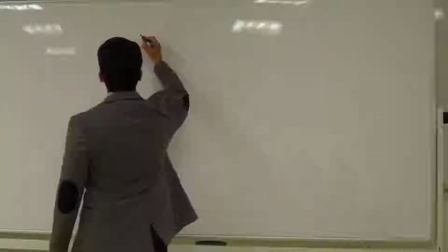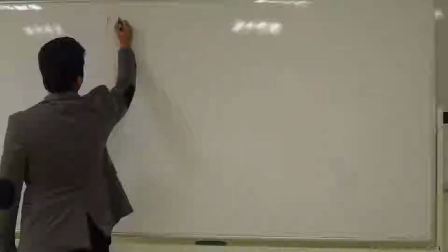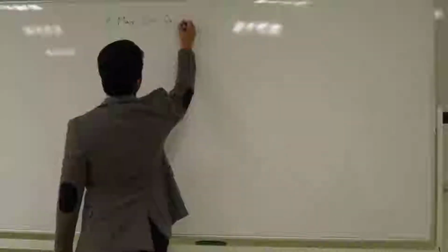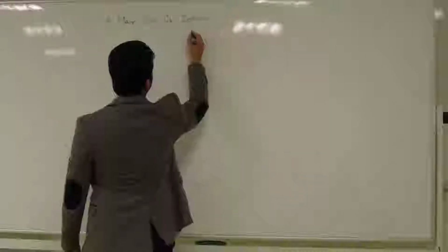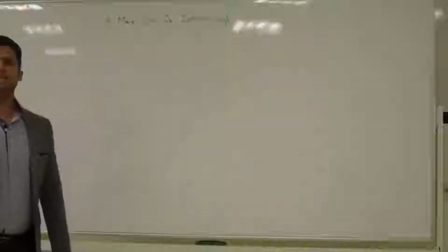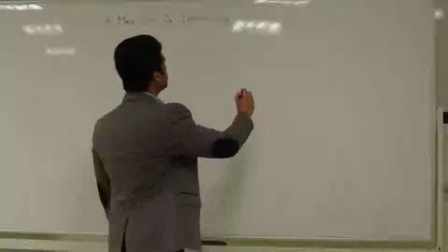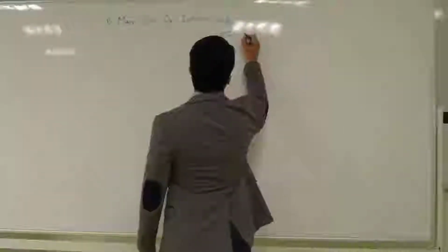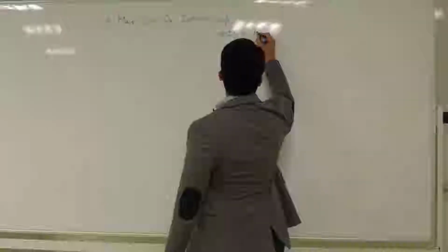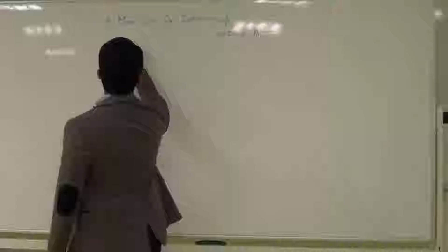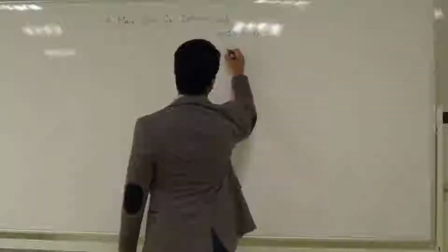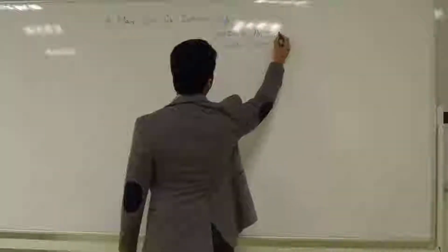The following steel. Number one, the main steel for the interior strip. How much is that? Tell me the spacing. Number 25 at the rate of 200 for interior. Okay, and similarly, the main steel for exterior is number 25 at 200, center to center.